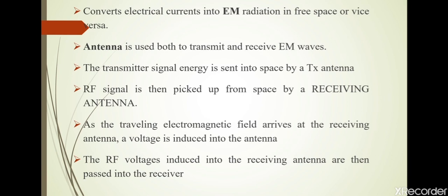The design of antenna system is very important in a transmitting station. The antenna must be able to radiate efficiently so the power supplied by the transmitter is not wasted. The dimensions of the transmitter antenna are determined by the transmitting frequency. The dimensions of the receiver antenna are not critical for low frequency. If the radio frequency signal increases, the design of the receiver antenna is critical.